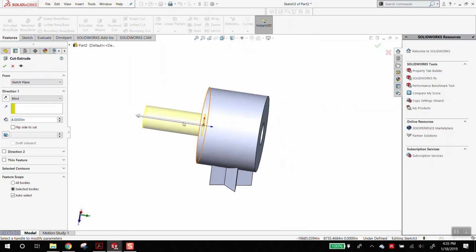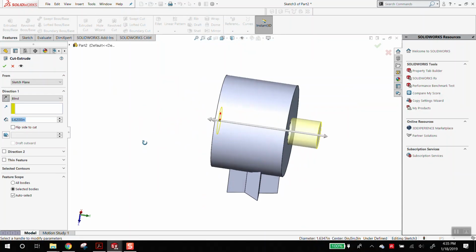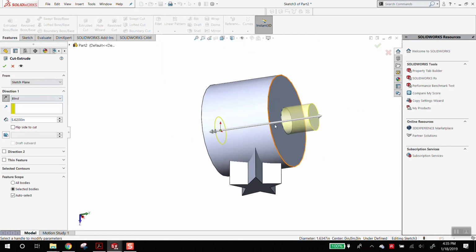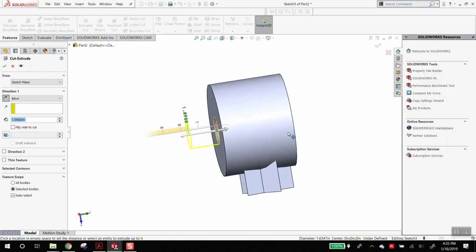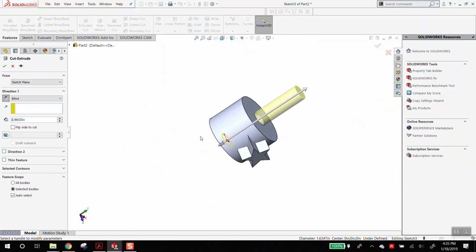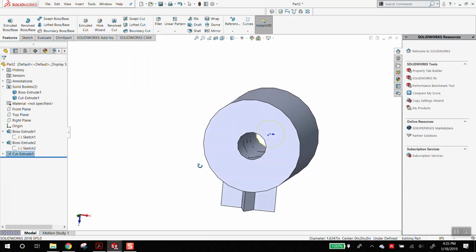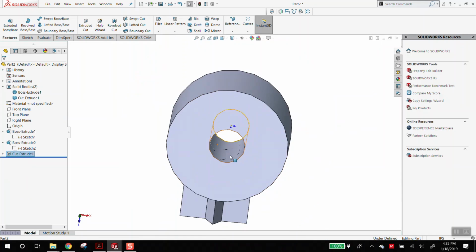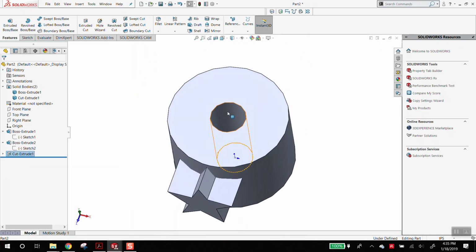Now it's just like extrude, it looks the same, but instead of being additive, it's now subtractive. You'll notice that there's this arrow. This is another way to change the direction, the angle. You can literally click and drag it. So I'm dragging this way now. I'm going to click the check box. Now we'll look inside here at the cut away star. Does everyone see that? And hopefully, again, you guys notice, just like a history in Photoshop, it now collects all of this information.